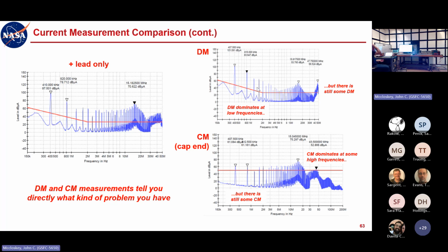But the power group has done that and has really done a remarkable job. And it's not just filtering, but they tend to put these converters in their own shielded compartment in any electronics box to ensure that all these currents have the best chance of getting back to the source where they belong, and minimize how much of this crap gets out and can wreak havoc on the rest of your system.